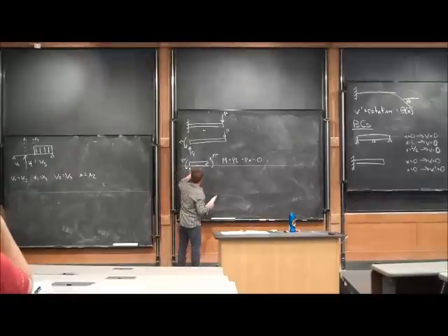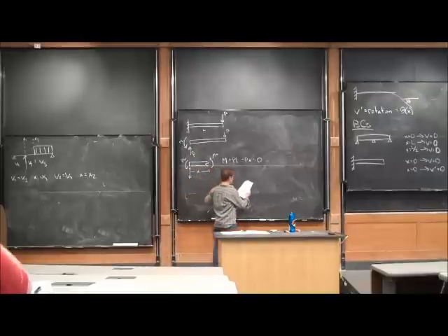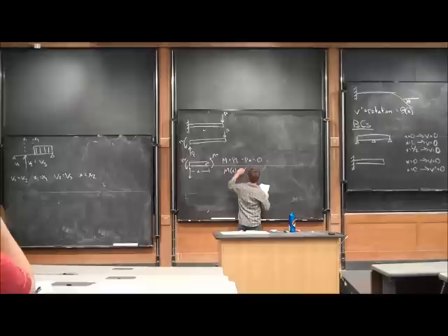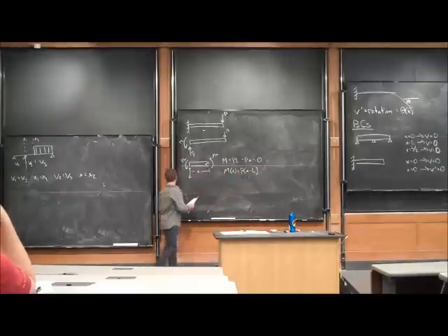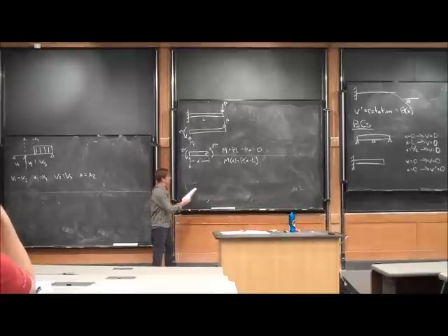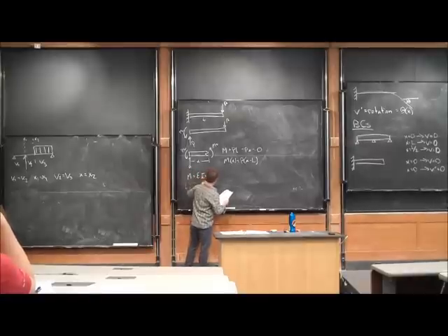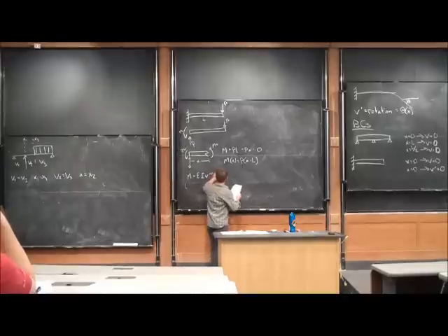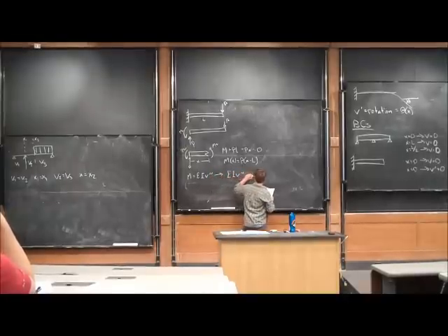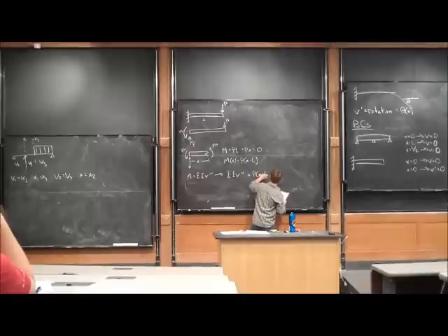Because this distance right here is our X distance. So, based off that, my moment as a function of X is going to be equal to P times (X minus L). Now we remember from what we just saw earlier in this class that M is equal to EIV double prime, which means that EIV double prime is going to be equal to P times (X minus L).